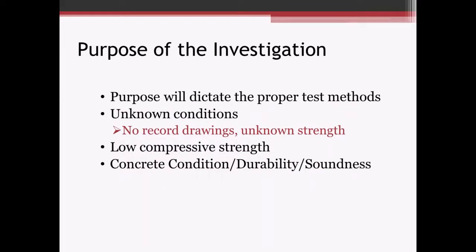So the purpose of an investigation is always going to dictate the proper test method, and a lot of times we might go out to the field with different tools in our toolbox. We might not be using just one tool, but it's because we don't know certain things. Maybe we don't have drawings. We don't know what the strength is. Maybe it's low compressive strength. We had some low break cylinders or something. We want to verify what we got in the field to give us a little more information.